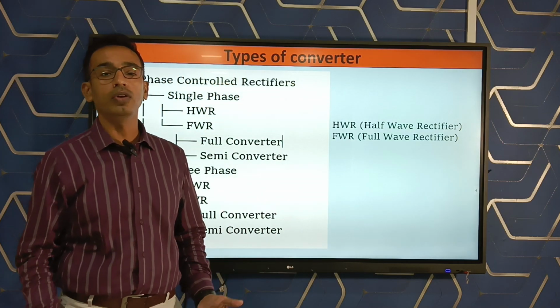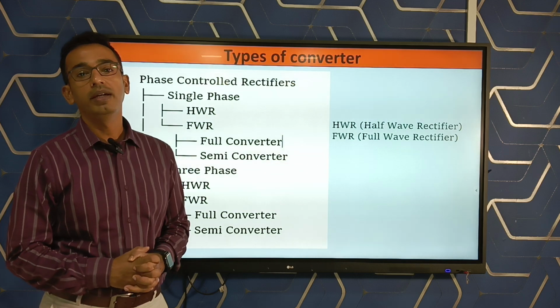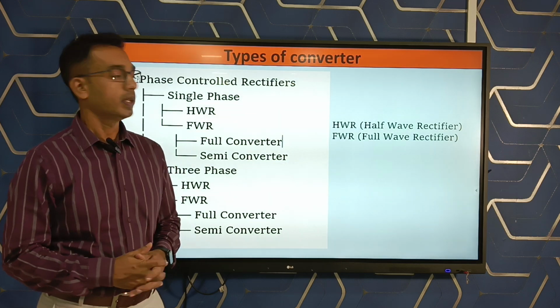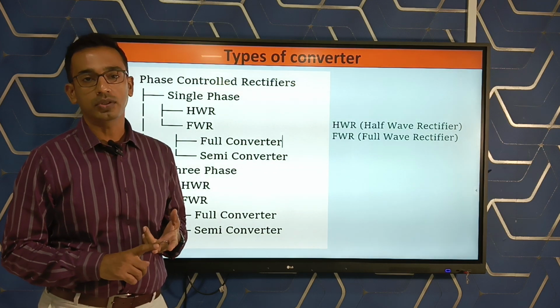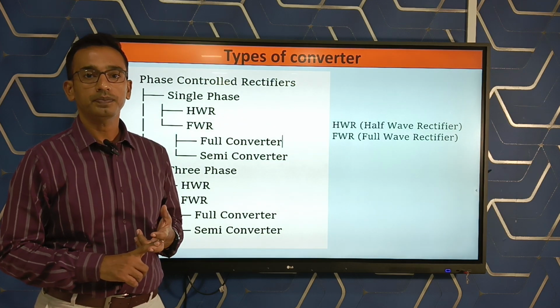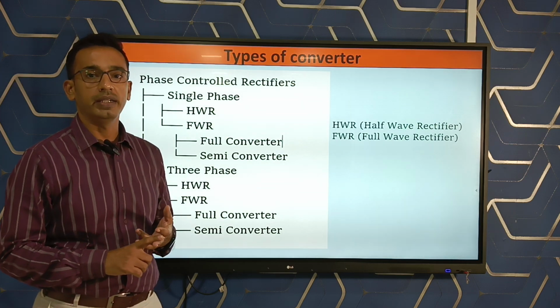Full converter means when four thyristors are used, that is called full wave rectifier, full converter. And the semi converter, when thyristor and diode both are used, that is called semi converter. So these are the classification of phase control rectifier.